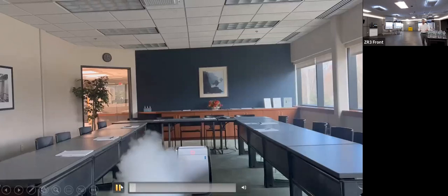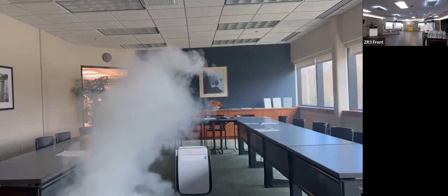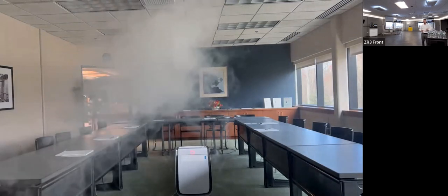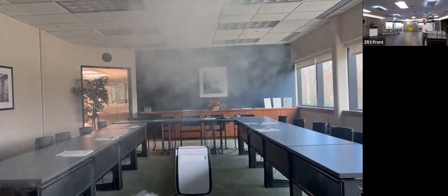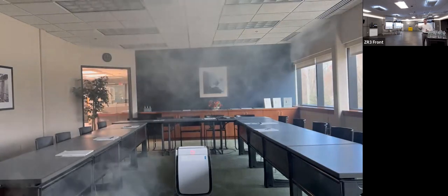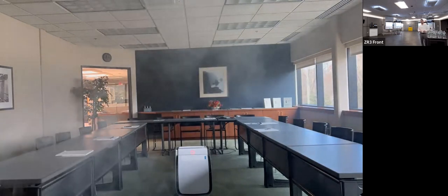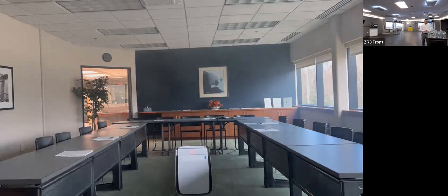As the smoke comes out, you would think that this system is going to suck in the smoke. What it does is contradictory to what we think it's going to do. It's taking that away and blowing it up, and then it's spilling it all across everyone's breathing zone. Imagine there's a bunch of people sitting at these desks. It's not truly cleaning the air. Eventually, over time, sure, if everybody stopped breathing and left that room, you'd eradicate any type of pollution in this room, but not while you're continuously generating emissions.